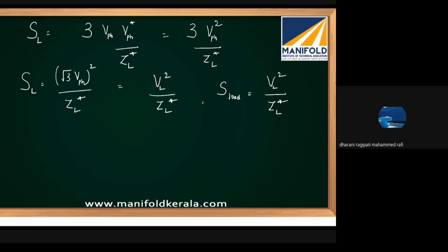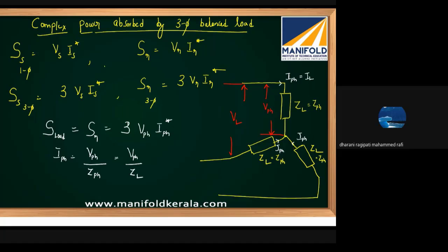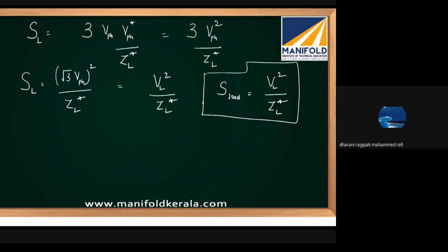Okay. So we have derived this, and you should never ever forget this formula. Very, very important, which we'll be using many times in power system. Now, sir, we have assumed our loads are star connected. Suppose the load is given in delta, what do I have to do, sir? Very simply, you just convert this delta into star.